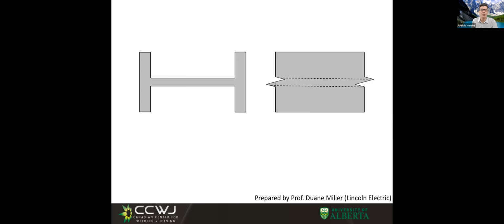How about if we want to do something similar with the I-beam or in a horizontal shape? Now, look at this. This design is not so good, right? What do you think about this weld here? Do you think this weld here is taking a whole lot of load? This weld here is not taking a whole lot of load because it's against the web that now, because the web is horizontal, is very compliant. So this weld is not doing a big job.